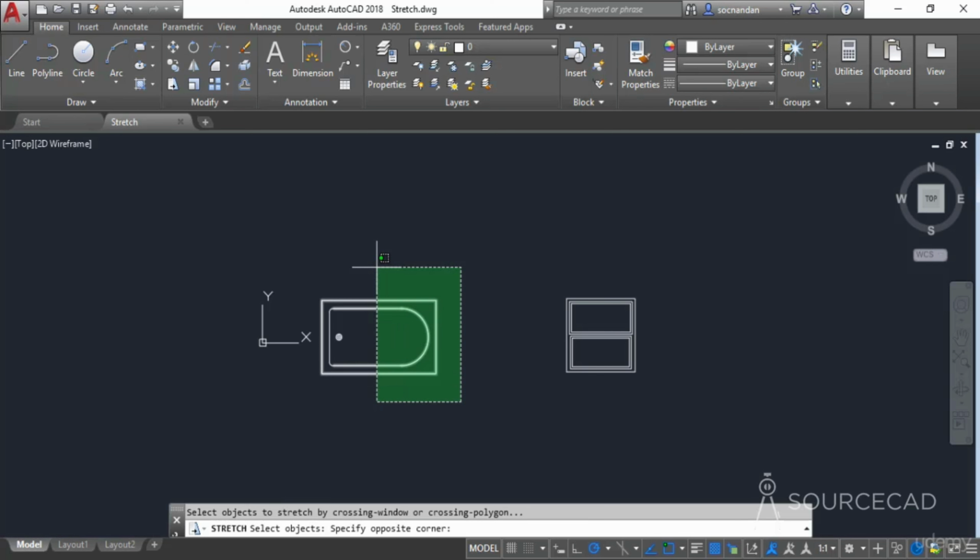Now all the objects which are completely inside this crossing window will remain unaffected, and all the objects which are completely outside this stretch window will also remain unaffected. So in this case, this line segment, this complete arc, and this line segment, this part of geometry will remain completely unaffected, but the length of these 4 lines will change, because in this case only these 4 lines are partially inside and partially outside. So now simply click at any point to make this stretch window and press enter.